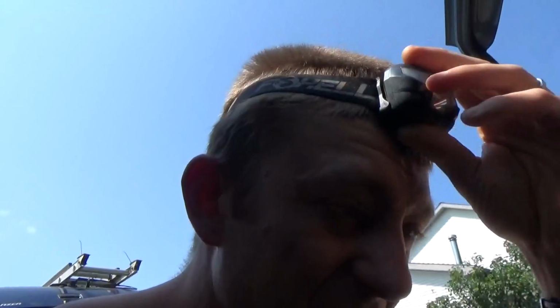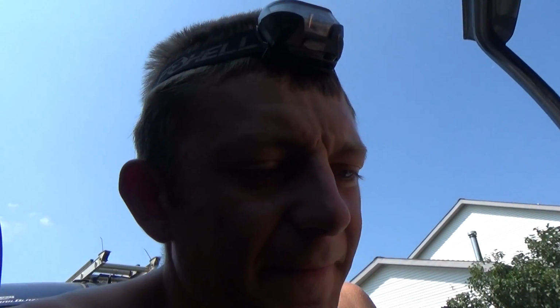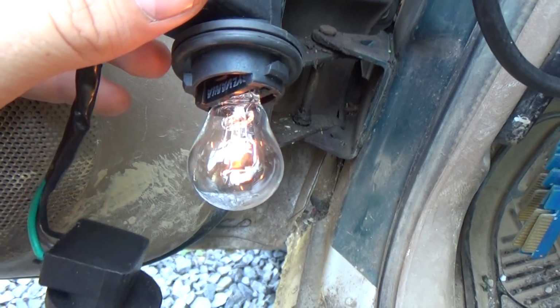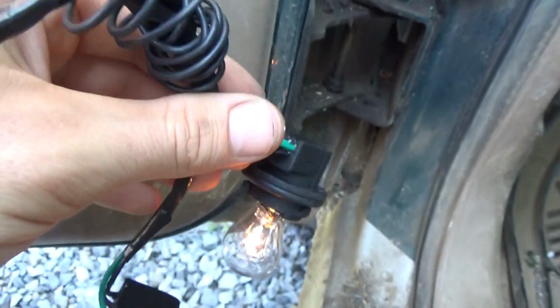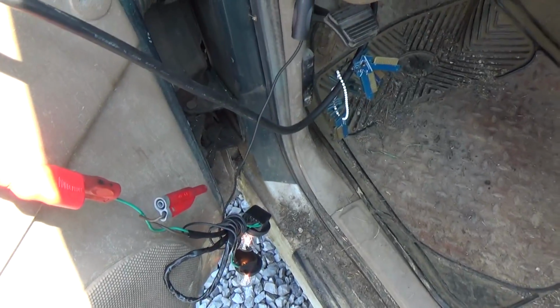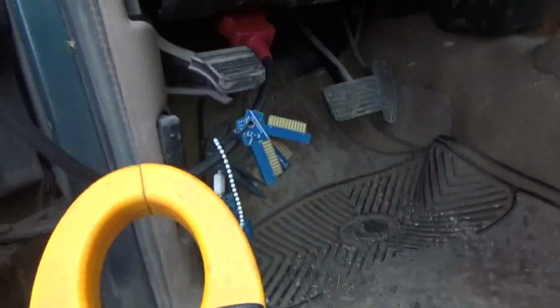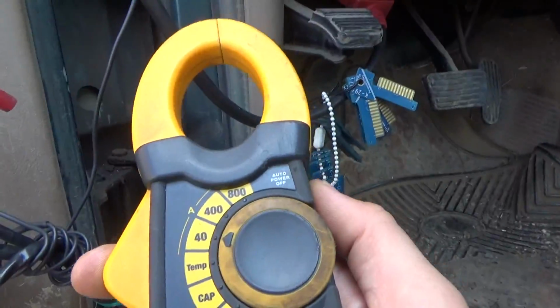So the plan of attack here is obviously a thorough visual inspection, especially around the oxygen sensors. You know, it could be rubbing on some heat shield. This truck is all rusty and beat. I would not be surprised if that was the case. And if we find a short to ground, these test lights will glow a lot brighter. So right now we can measure the current. It's, I don't know, probably a few amps. So let's do that just for reference. All right, let's see how many amps we have, and we're going this way.